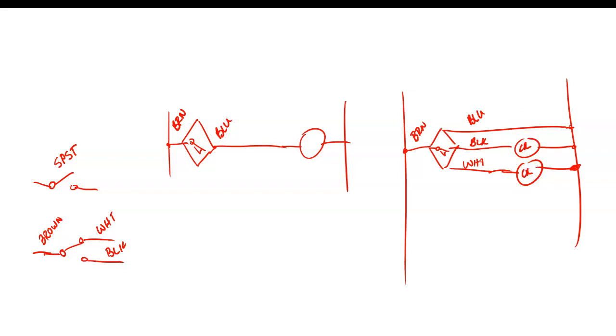And they're single pole, double throw control relays, and we'll have to figure out which one. And then what we'll do is we'll come down here and we'll use a CR contact to do whatever we want to do. I'm just going to put a light bulb up there. But we might call it CR1 and CR2, right? And I don't know which is which. I don't know which relay they have connected to which output. So that's something you'll have to figure out when you trip it to see if the light comes on. If it comes on when it's supposed to go off, you'll just move it over to another terminal, right? Everybody okay?